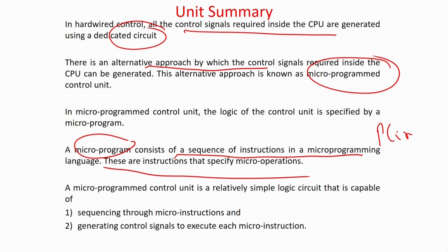The microprogram control memory is very similar to a normal memory, but we allocate it separately for the microprogramming based control. So, we call it a microprogram memory. If we can put these control signals explicitly in some memory locations, then when you access that word of the memory, the corresponding control signals will become 1 and 0 as required. That is the idea of microprogram based control. For each micro instruction, the control signals that have to be made 1 and 0 you directly write into one word of the memory, and then step by step you go from one location to another and so forth. So, a microprogram control unit is a simple logical circuit.